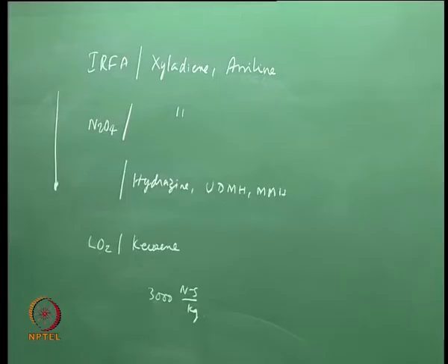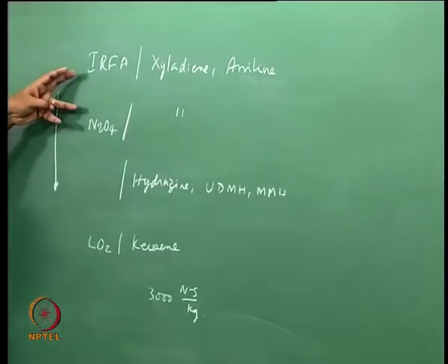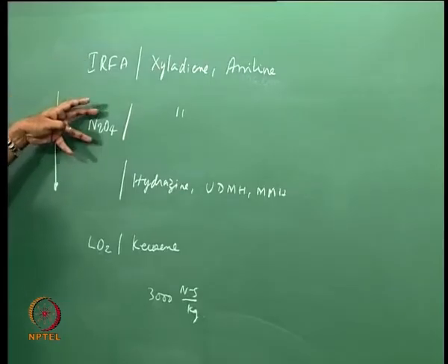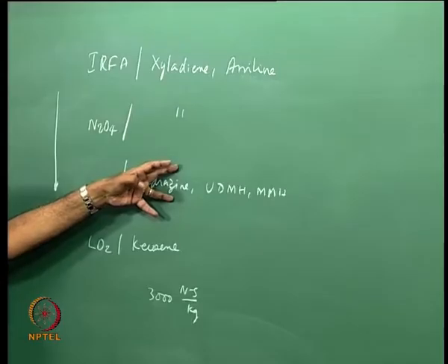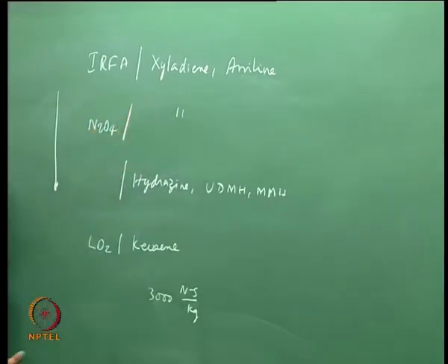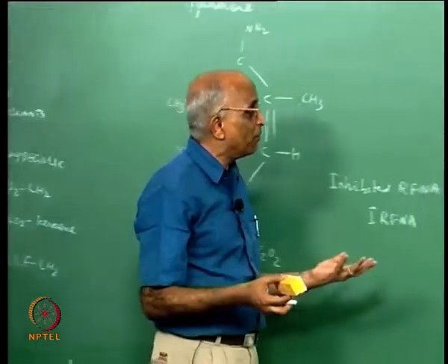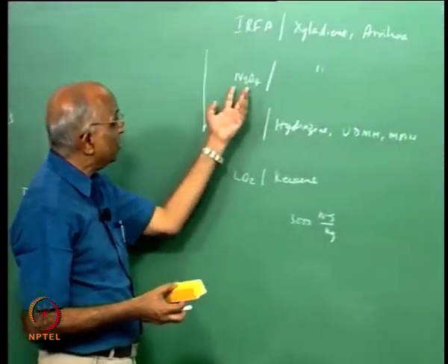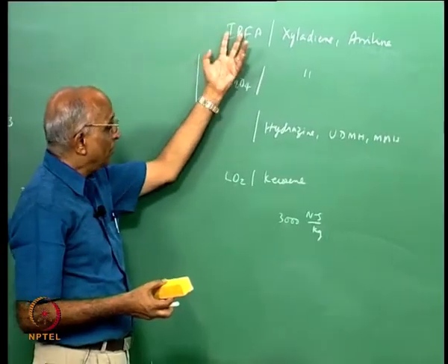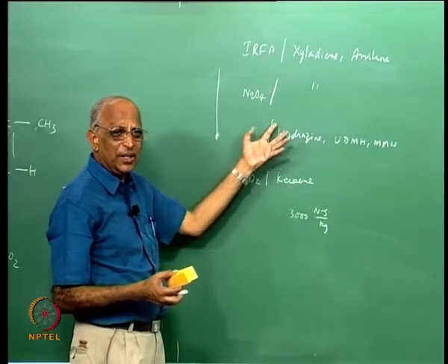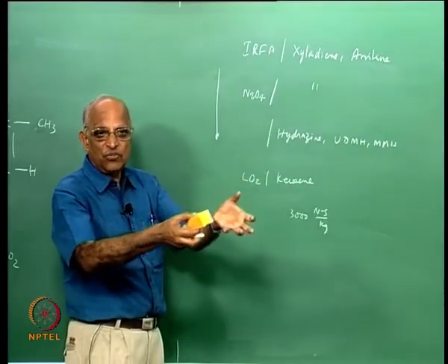Therefore, these are the low energy propellants, and many of them, especially those using nitric acid and N2O4, are hypergolic, which means they are much easier to use, and that is why we see these fuels being repeatedly used in spite of being carcinogenic. It is much easier to use, and also the system becomes very simple. You do not need an auxiliary igniter; whenever you want, you just fire it.